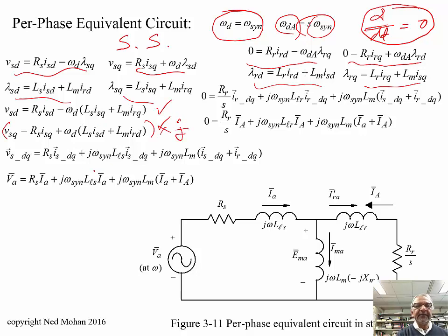And so we get this equation here, and then we know that a space vector in steady state has some relationship to a phasor in phase A. It's the same orientation, just a slightly different amplitude. So we can write from this space vector equation Vs dq the stator phase A voltages and currents. And the same thing we can do for the rotor circuit.